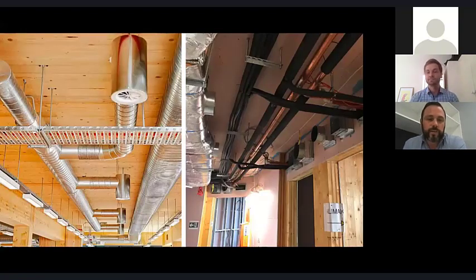And look, it leads into discussion about services and coordination of services in your design, but also thinking about the constructability. And what you see here is an image of 55 South Bank, which needed to be fully encapsulated. And then you've got the Lend Lease commercial office style, which is exposed soffit and services installed. So my point here, away from the service penetrations and all of that, is the sequencing, having to put the fire-rated plasterboard on first, then the services, in comparison to just putting the services on.